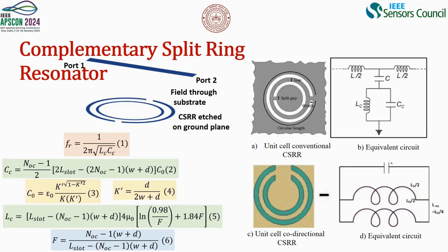It's basically, we can say, the mirror image of a split ring resonator, developed in terms of Babinet's principle, and it is excited using the most popular microstrip line, where if we incident an RF signal from one port, the axial component of the electric field becomes perpendicular from the top plane and gets confined to the bottom plane, where it excites the complementary structure that has been etched.